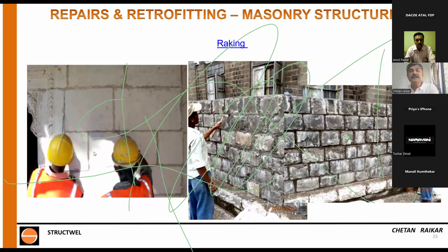As far as this masonry you see on the left hand side, it's a sandstone masonry. On the right hand side, what you see is basalt. Basalt is a very, very strong stone. Use cement mortar in basalt, it doesn't matter. It doesn't hamper it. Even granite is extremely good. These are igneous rocks, which are very, very strong. So nothing happens if you use cement mortar in stone masonry of basalt or granite. But otherwise, for all other stones, I strongly recommend you can use cement inside, but the surface has to be with lime. The top 1 centimeter, 2 centimeters of the joint has to be with lime in sandstone and limestones.